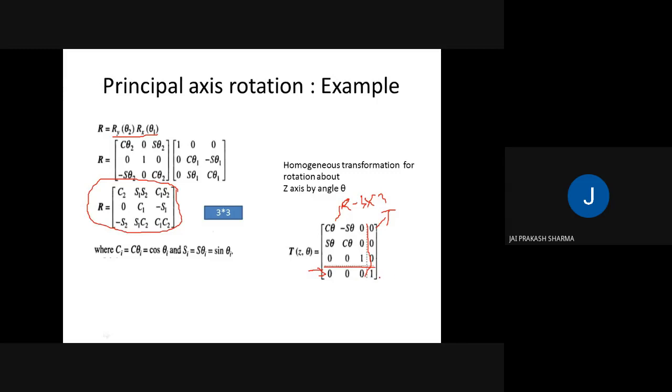And at last, if we are going to perform scaling, we have to use different values as we are performing scaling. But in case of robotics, whatever the configuration of the practical model and whatever we are simulating, it is going to be common, so in robotics we always use a scaling factor of 1. If we are going to use a vision system, then these values are going to change. So for collaborating all these four operations, that is rotation, translation, vision system and scaling factor, a complete 4 by 4 matrix is used for evaluating the final tool position of our robotic arm. So this is called a homogeneous transformation matrix.